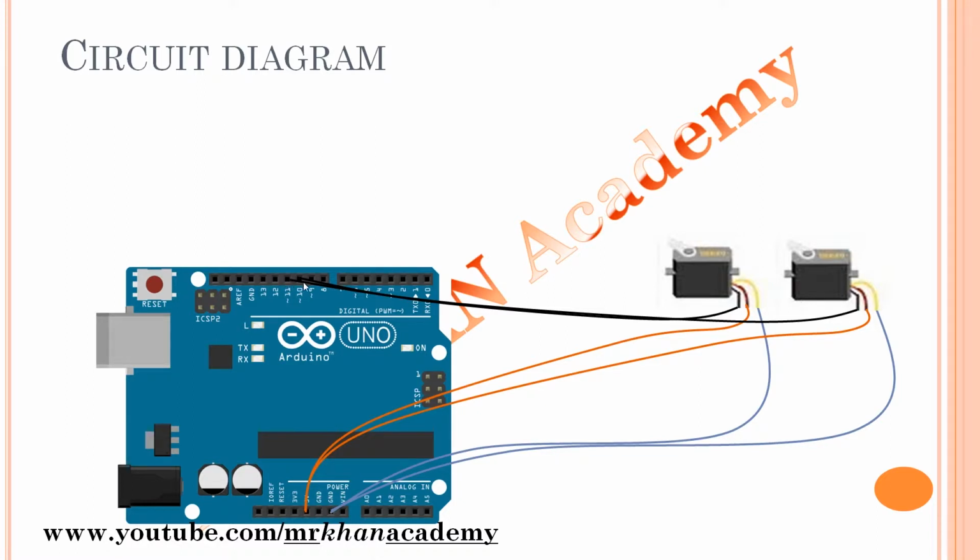Instead of 10 and 11 you can use 9 and 10 also. Might be in the code I use 9 and 10 only. Here I am showing the circuit diagram with 10 and 11, but you need to change the code accordingly. And the other two wires are the power supply, 5 volt positive supply, and the last one is the ground. This is the simple circuit diagram for the two servo motors.